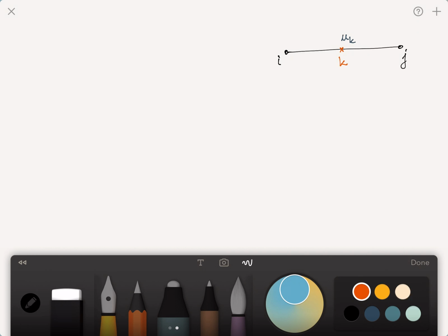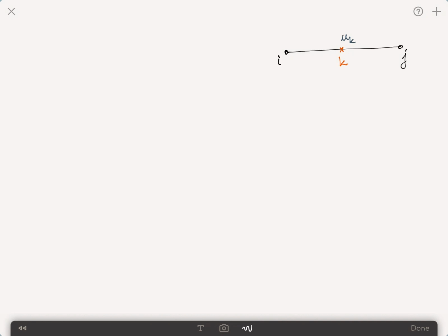And the other way of doing it is by introducing a degree of freedom by introducing a node k, but instead of saying that they are 2 different elements, we will say that they are the same element. It's exactly the same element now. The element hasn't changed, but there are 3 nodes in the same element. So in order to describe this one element, I will have to change the approximate behavior of the function.